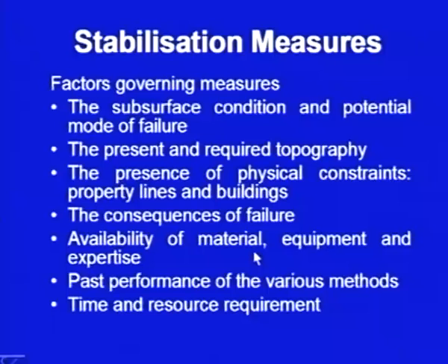The second point which I would like to discuss is about stabilization measures. We have discussed that some permissible values of the factor of safety will be there, let us say 1.5 or 1 or 2. So, whatever the factor of safety is, based on this we will decide whether we have to stabilize the slope, whether it is stable, whether it is safe or unsafe.